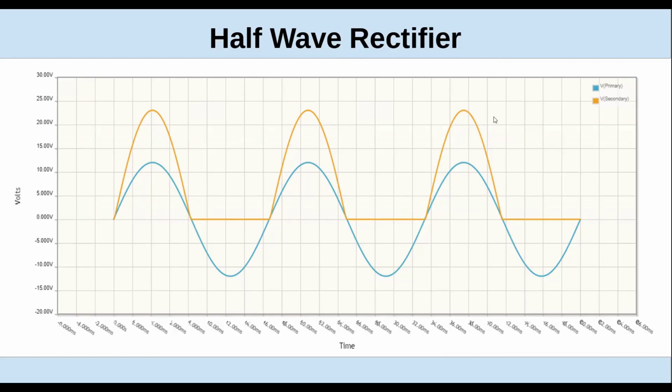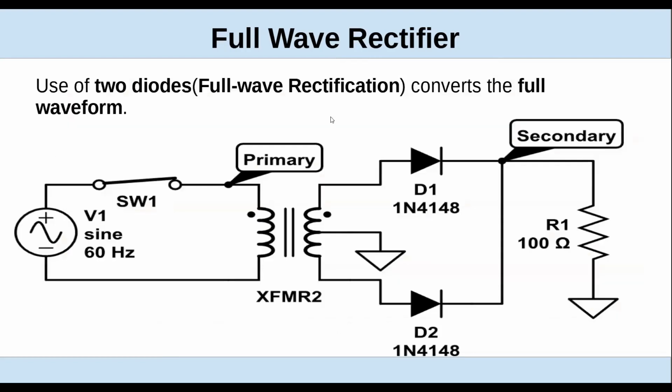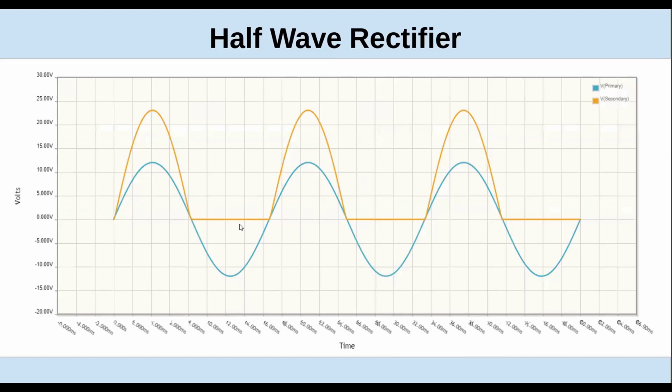If you filter that with basically a low pass filter or integrator, you can smooth it and get almost a constant DC. So the voltage will be the same through the diode. It'll come in at, let's say, 10 volts AC and come out 10 volts DC because it's only taking a half wave. It's going to be less than the peak.